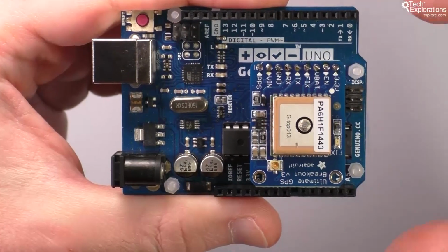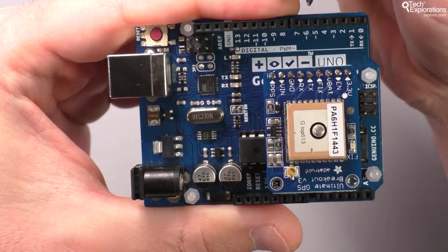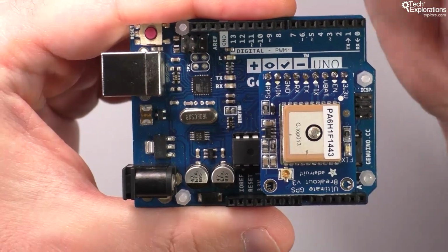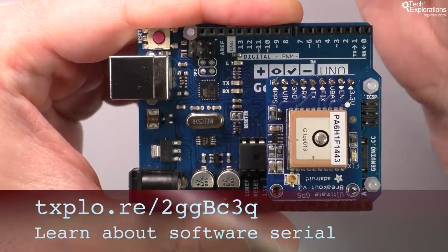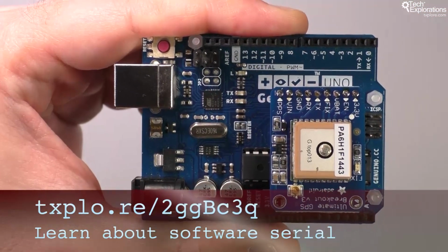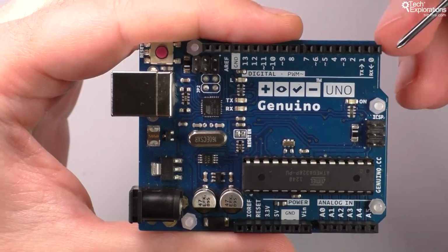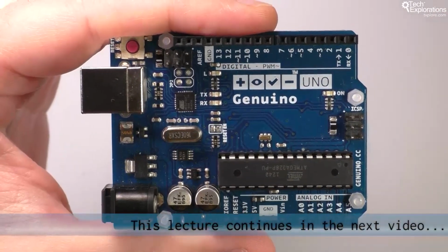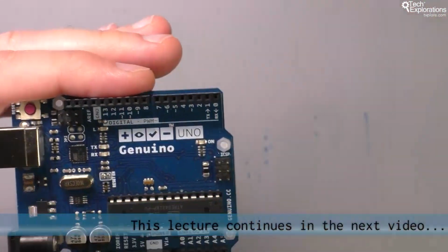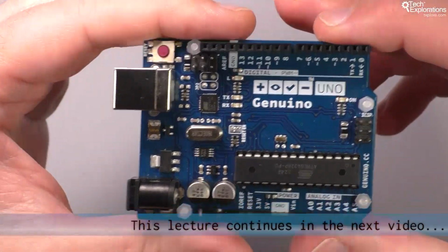What we can also do is to implement the same functionality using any other digital pin pairs, but emulating the hardware serial functionality that comes with the Arduino. So we use software to simulate the hardware, and that gives us access to additional UART channels, additional serial interfaces. Another common use of the serial interface on the Arduino, other than connecting it to your computer or to devices like this GPS module, is to connect multiple Arduinos together and have them communicating via the serial interface. Just a very simple way to do so.